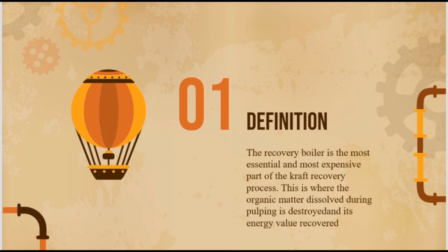Recovery boilers are an integral part of the steam and power balance in a plant. The economic viability of the plant is highly dependent on the efficient and reliable operation of the recovery boiler. Recovery boilers accomplish three main tasks: burns black liquor, recovers inorganic chemicals for reuse, and produces superheated steam.